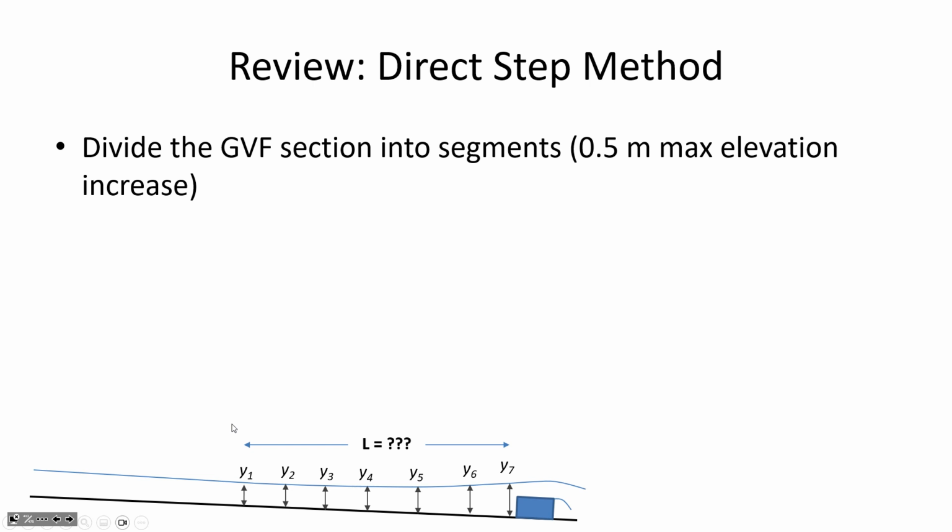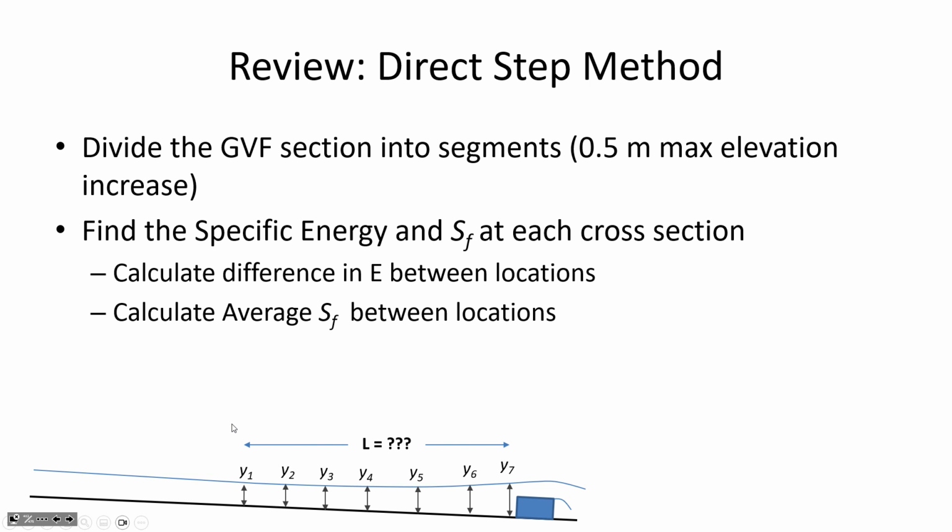They're irregular in shape. If you've ever driven alongside a creek, you can see that the creek maybe is collapsing in on itself at one property. Another property, they've lined up rocks and bricks and tires to try and prevent some kind of erosion of the channel. So the geometry is really irregular. And the direct step method doesn't have much applicability to any channel except for a channel whose geometry is remaining constant.